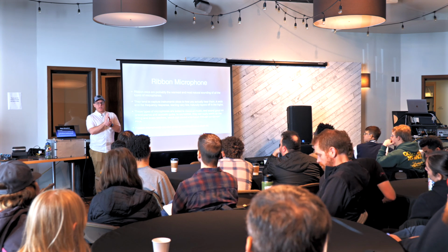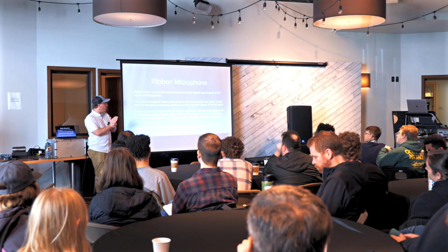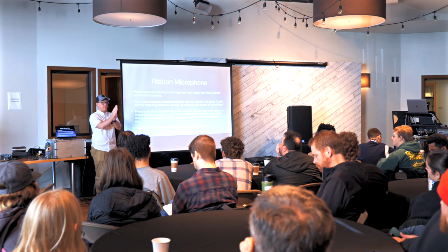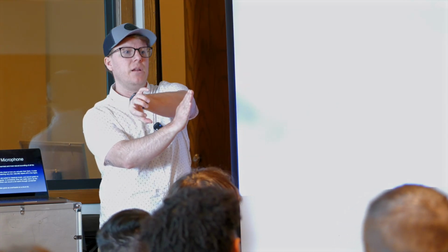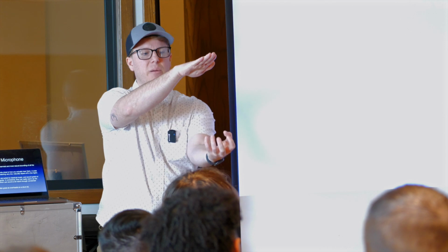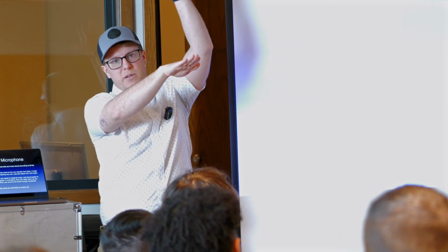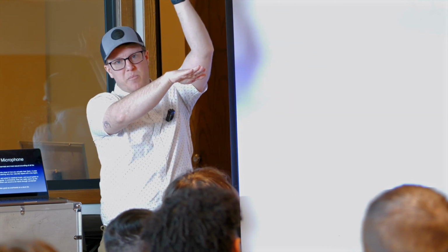So I like to think of them as the closest microphone to our ears because there's a diaphragm on both. The diaphragm picks up sound pressure from both sides of the microphone, and you can get really creative with mic placement with that. I'll get into polar patterns, but they pick up as a figure 8 polar pattern. If you place them like this, you're going to pick up sound from here and here, or you can place them like this and you're going to pick up sound from here, but then also whatever's hitting the diaphragm and moving past it. If you don't own a ribbon mic, buy a ribbon mic.